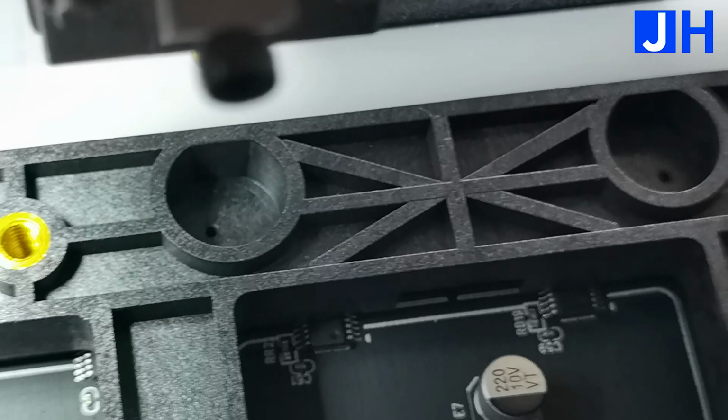Open this Z-axis setting. After clicking, the window pops up. Start address coordinates, enter 1. The end address represents the last coordinate. Since there are 64 coordinates in total, enter 64 or 100. And then we input the height in the Z-axis: 76.4. Then click OK. You see all the Z-axis heights have been modified.